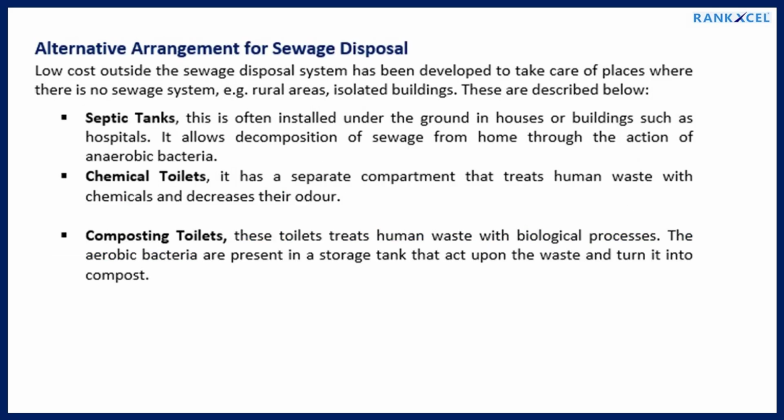Alternative arrangement for sewage disposal. Low cost on-site sewage disposal systems have been developed to take care of places where there is no sewage system, for example rural areas and isolated buildings. These are described below. Septic tanks. This is often installed under the ground in houses or buildings such as hospitals. It allows decomposition of sewage from the home through the action of anaerobic bacteria.